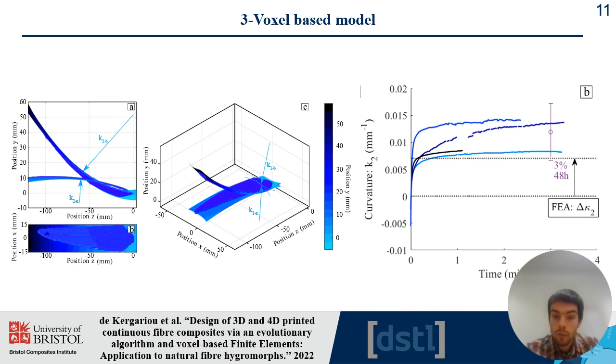And the smaller the distance, the more sensitive it is to this perturbation, and therefore the small distances that we have been measuring had a lot of variability in the results. The other element is the coefficient of moisture expansion that depends on the distance between surrounding fibers. It varies with the distance from one fiber to another one, and as we consider only a constant value for the coefficient of moisture expansion, this introduces errors in our test. We also discuss other influences for this difference between experiment and model, and we encourage you to have a look at the paper if you are interested in this information.